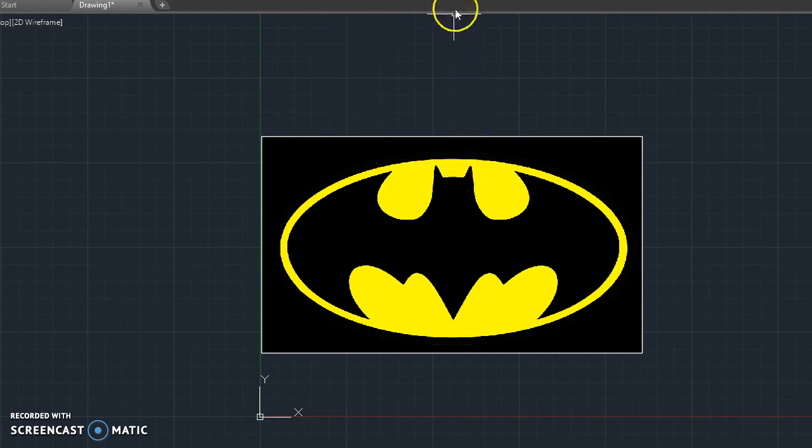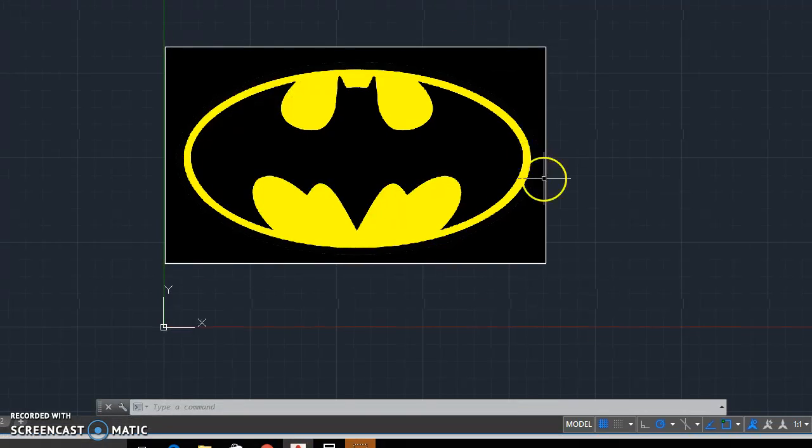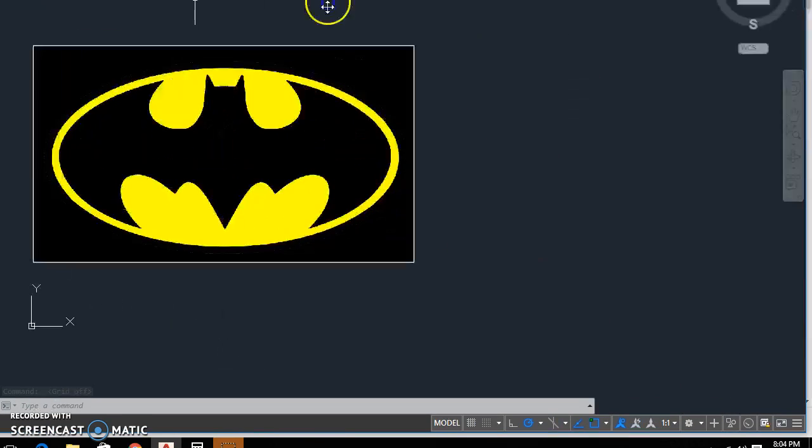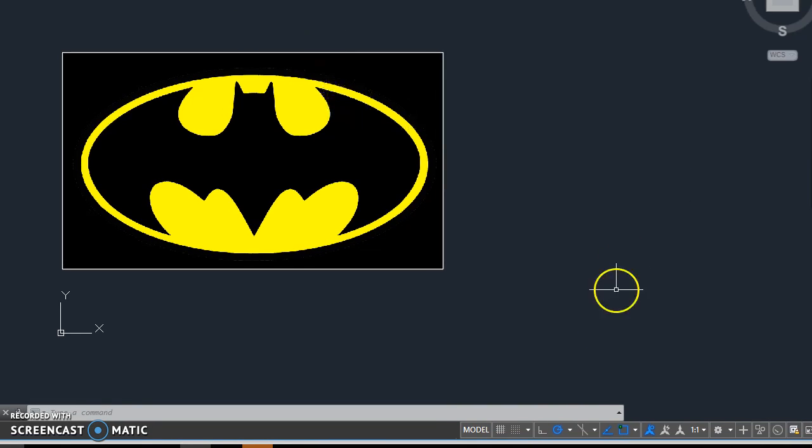All right, a few things before I get started. I hate grids. This is optional. Turn off your grid. The grid is just going to mess with your head. It doesn't help you out at all. It's just going to annoy you. Looking at the bottom right hand part of your screen, I should have showed you this already, but if not, I will. Do not turn that on. That's snap mode. It will snap onto a quarter inch.